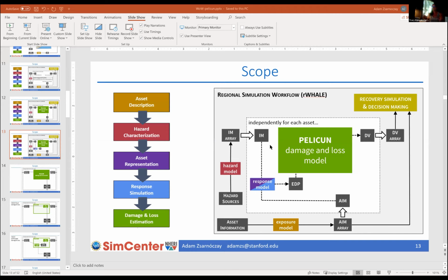So in theory, if you wanted to pick a set of footprints of buildings in the immediate vicinity and run a higher fidelity simulation locally there to capture local wind effects, and nest that within the larger simulation where we're using a more crude approach to account for that kind of interaction effect, that kind of local topography, using land use land cover, then I think that kind of nested simulation creates an interesting opportunity that is currently not in the framework, but could be a way to contribute.